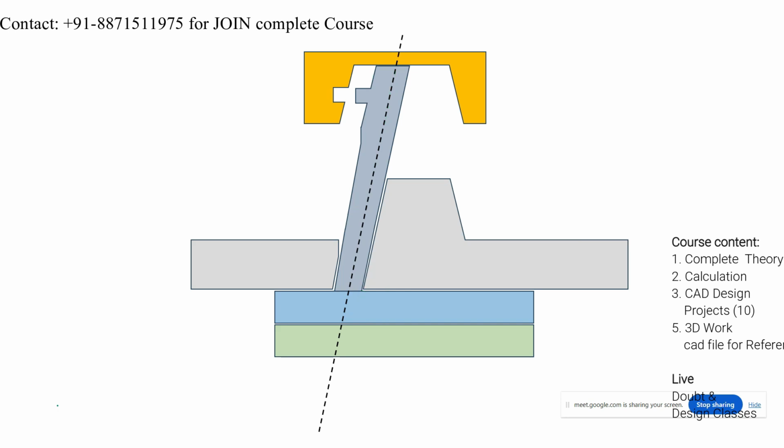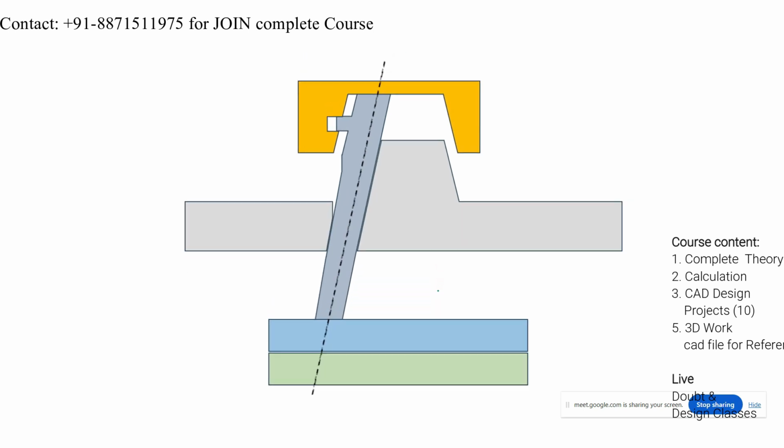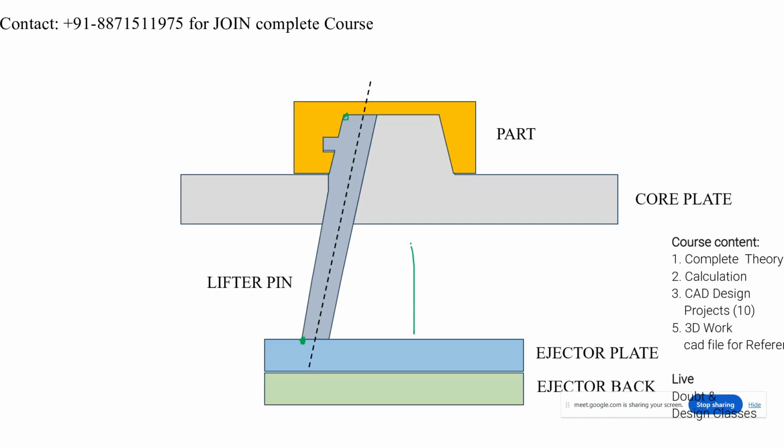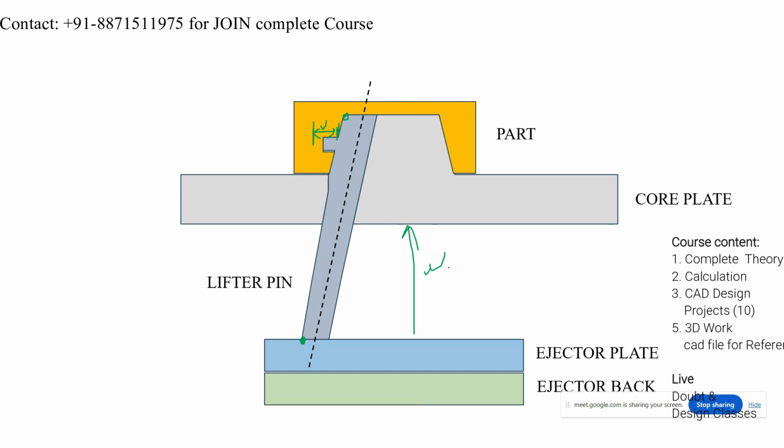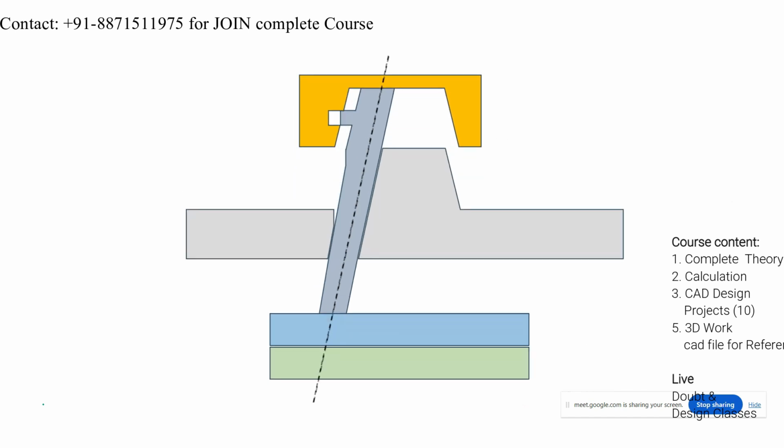Understood? Is the angle fixed or not, sir? The angle will be fixed, but we have to calculate the angle depending upon the stroke and how much ejector stroke we need. Depending upon the ejector stroke and the stroke required here, we have to calculate the proper angle. Is there any particular formula? Yes, see here, simple trigonometry.